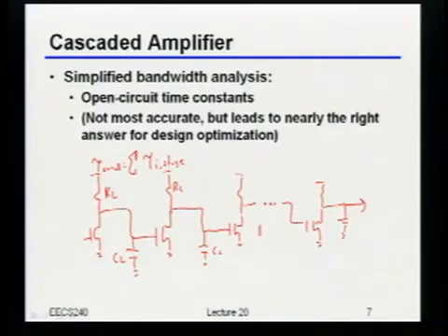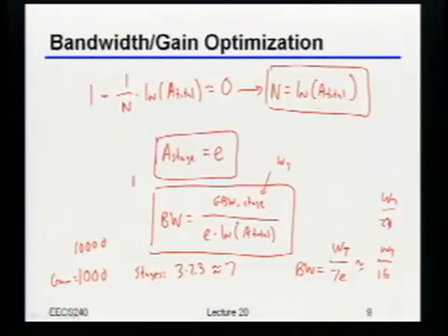But it actually turns out, the reason I even mentioned the buffer problem, by the way, is because you can actually use almost exactly quote-unquote logical effort, or like the digital sizing problem. You just have to sort of notice that here, what we called fan-out was gain. Okay? But so if you wanted to extend this to analog, all you have to do is define a new fan-out, which is gain times the actual capacitive fan-out.